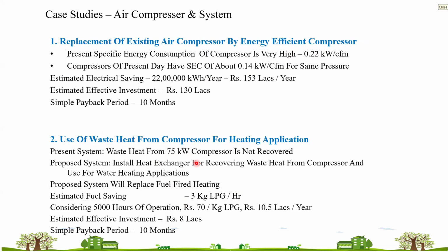Sir, what is the benchmark for this? I mean, kilowatt per CFM, the lower the kilowatt per CFM the better, always better. There is no benchmark. Everybody claims our compressor is best. You can calculate those: let's say 15 kilowatt for 100 CFM, 0.15 is there. Another compressor is saying that for 100 CFM we require 18 kilowatt, 0.18 is there. So you can directly correlate those. Okay.